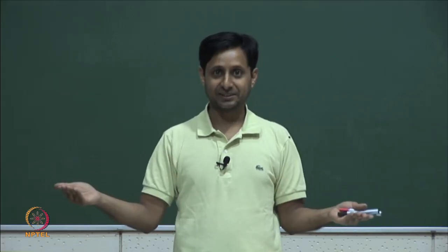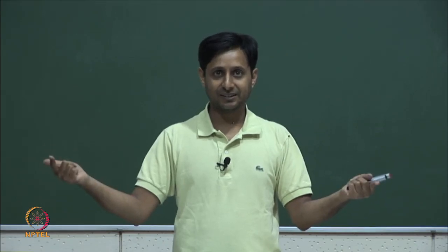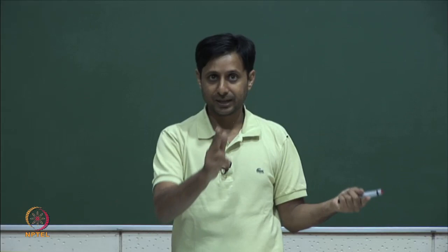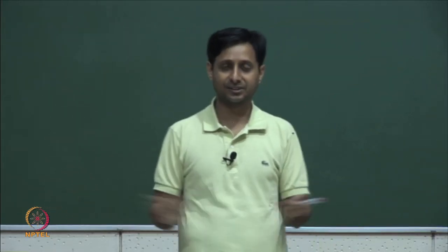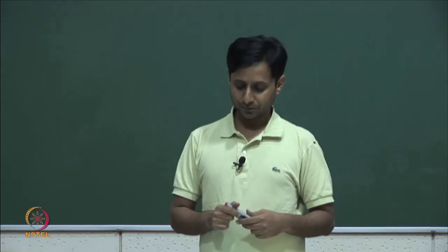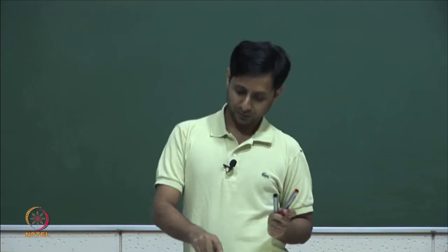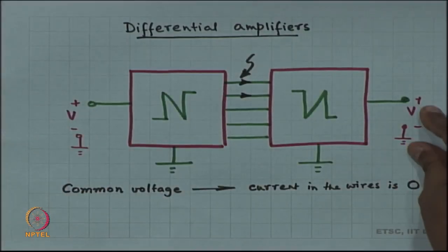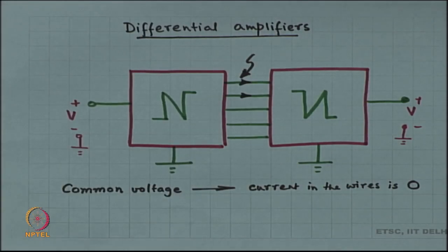In any case it is a wire, it is establishing equal potential, and then the current is 0 through it. So, therefore, I can cut the wire and KVL, KCL is not going to be violated on the other two sides. So, this is something important. So, if I apply V and V over here, then it is okay for me to cut the wires in between. All right, this is experiment number 1.